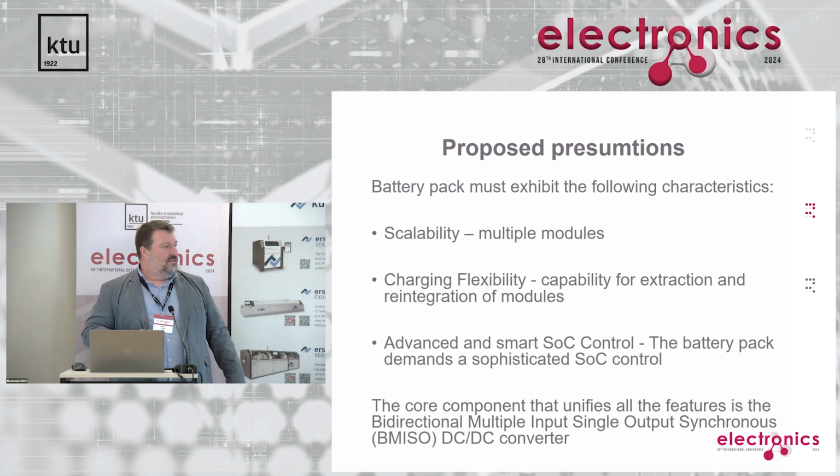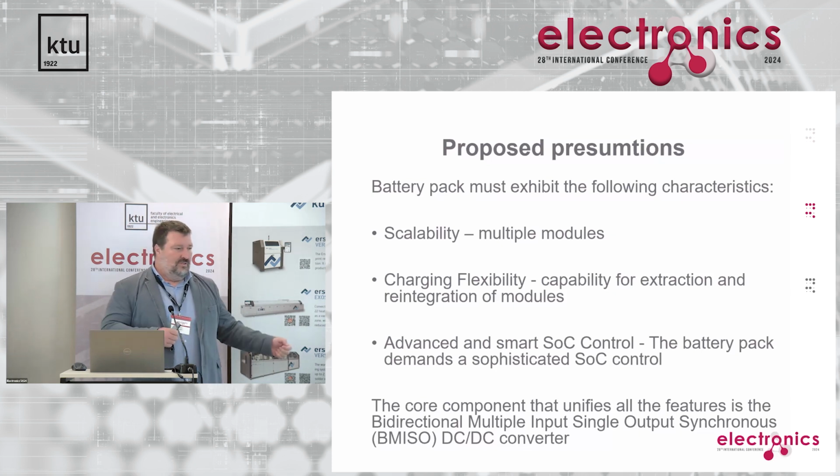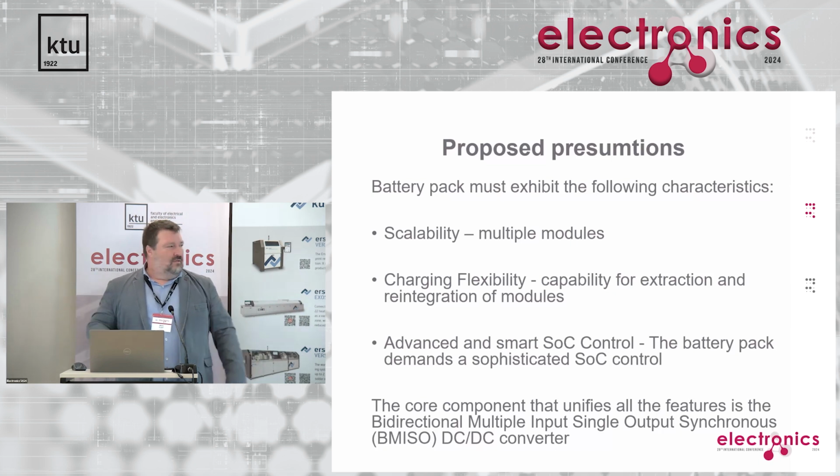Charging flexibility also, so the possibility that you at any point extract one or several modules and replace them with full ones. And of course, since everything is working according to state of charge of each module, you have to have advanced and very smart state of charge control here.